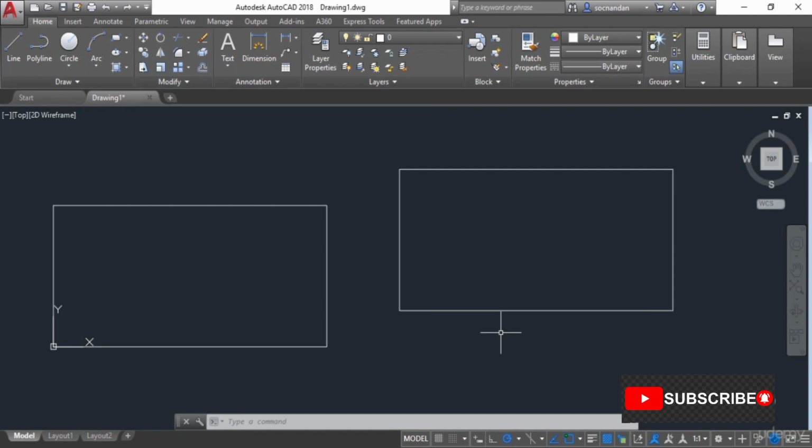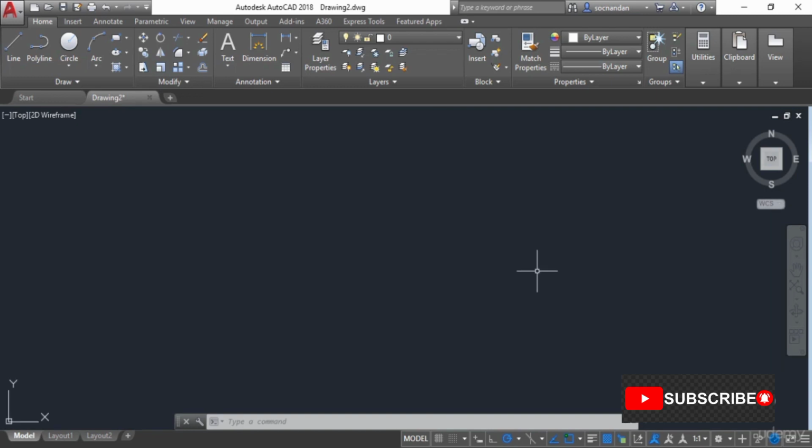In the next lesson, I will tell you about making the lines or making the geometries using the polar coordinate system. In the previous lesson, we made a simple rectangle using the line tool, and we used the simple Cartesian coordinate system, and we also used the direct distance entry method and the relative coordinate system. So we have used multiple different methods to make the same rectangle. And now in this lesson, I will tell you about making lines which are inclined to certain angles, and for that we need polar coordinates.